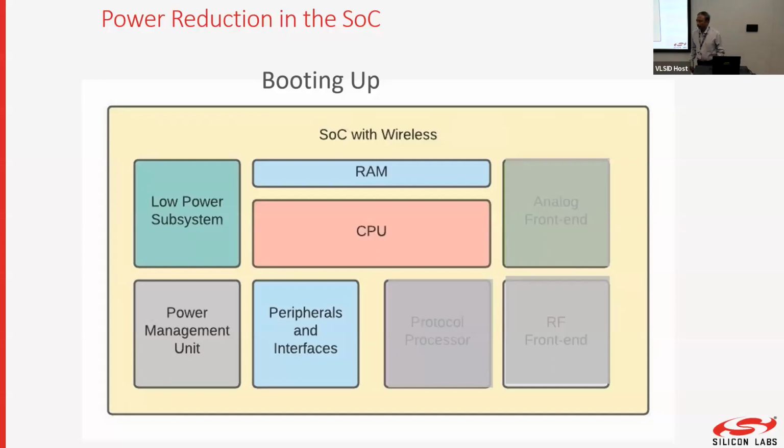Is it the same for high frequency and low frequency? No. If you run a microcontroller at 250 megahertz, it will certainly be drawing higher current than if you're running at 25 megahertz, because in CMOS circuits, the clock rate and the current consumption are kind of proportional. Actually, the slide is showing that. Anyway, we'll come back to it later.